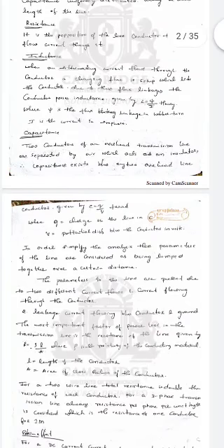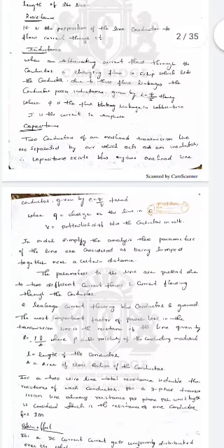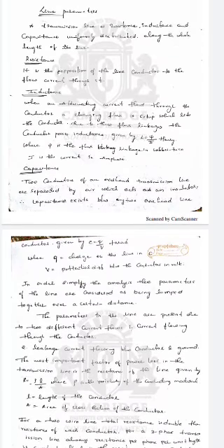Here, if you observe, R is directly proportional to the length of the conductor. Just imagine, since transmission lines are very long, especially for long distance transmission lines, that is long or medium transmission lines, the resistance will naturally be high. So it becomes a very important task to manage this resistance of the transmission line. This will be taken care of before the transmission lines are manufactured.